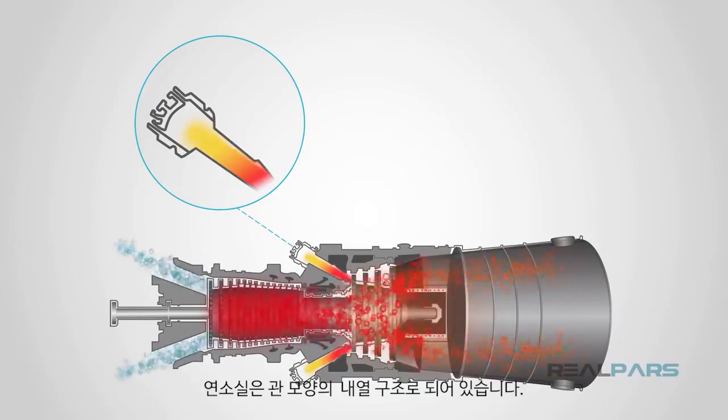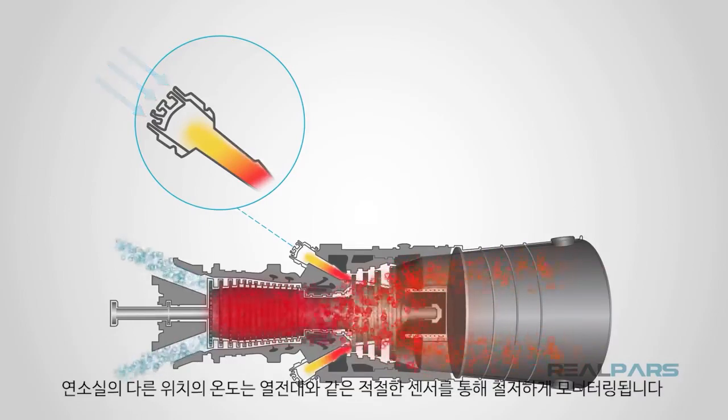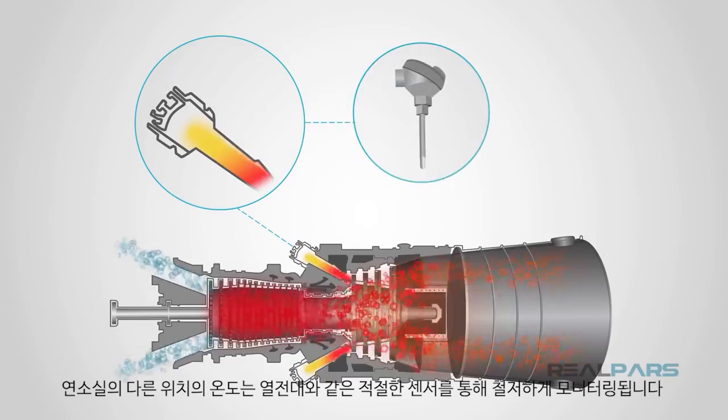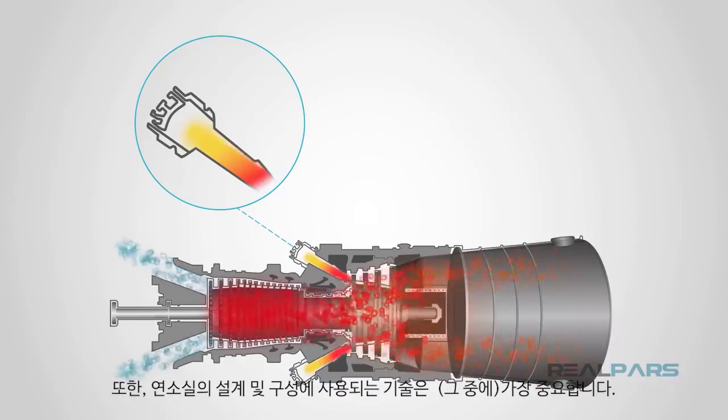Combustion chambers are of some tubular heat-resistant structures, and fuel is usually injected into it from the circumference and at different cross-sectional locations. The temperatures at different locations of the combustion chamber are thoroughly monitored by means of proper sensors like thermocouples. This high-temperature, high-pressure zone in a gas turbine structure is of the highest levels of importance to monitor and control. Also, the technologies used in the design and construction of the combustion chamber are of the topmost ones.